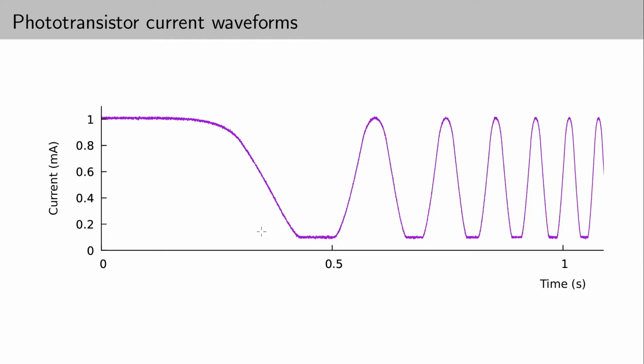And so what you can do with these simulated current traces is use them to drive LTSpice simulations. LTSpice has a way of setting up current and voltage sources with data files as input. LTSpice calls them PWL files, for piecewise linear.